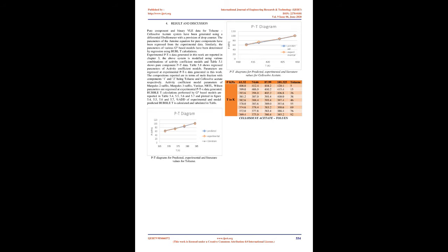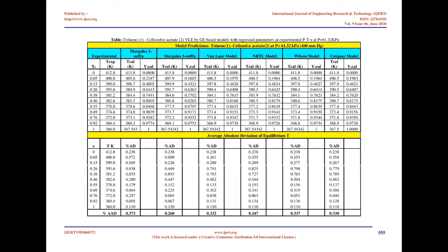Vapor-liquid equilibrium, VLE, is a condition in which a liquid and vapor phase are in equilibrium with each other, a condition or state where the rate of evaporation equals the rate of condensation on a molecular level such that there is no net vapor-liquid interconversion. A substance at vapor-liquid equilibrium is generally referred to as a saturated fluid. For a pure chemical substance this implies that it is at its boiling point. Such VLE information is useful in designing columns for distillation, especially fractional distillation.